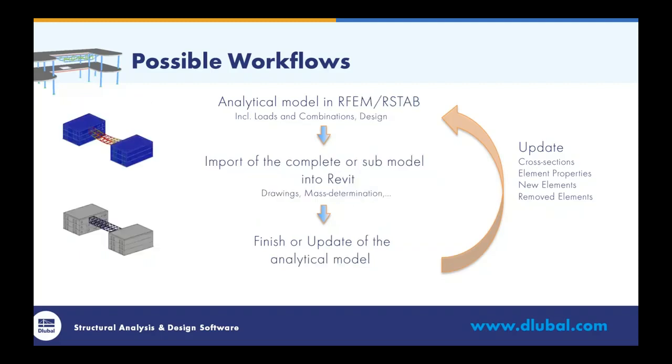And then there's the third workflow, and that's working the other way around. So here you would start in RFEM or RSTAB. Maybe you're the structural engineer and you made a preliminary design of that structure in RFEM. And now you want to make a few drawings in Revit, you want to determine the masses. So you can export the RFEM model into Revit, into a completely empty Revit file. So this is also possible.